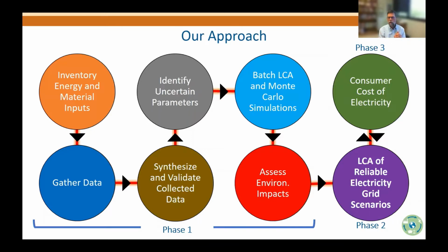Now, one of the questions that Fu Zhao had to answer was, in looking at GaBi versus SimaPro versus OpenLCA, these are the platforms that are pretty much available globally to do LCAs. We're using OpenLCA as our platform, in part because it can be readily written into Python scripts, and they have internal Monte Carlo capabilities so that we can run thousands of simulations by having a variance of a range of parameter values within an envelope that we can set.